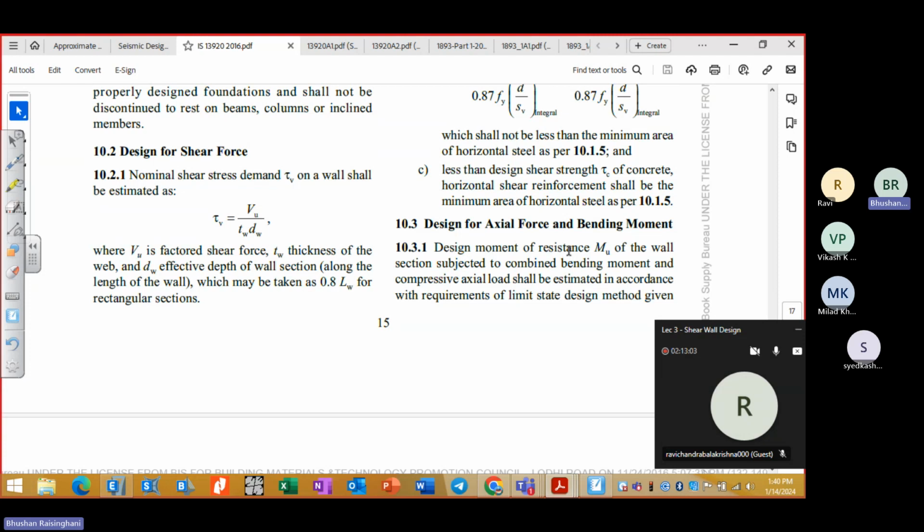There is a P wall software, in which they have given the calculation of how you can find it. So I'll share in the group how they have done it. P wall is a separate software that is based on ACI code for design of the shear wall, and you can compare the results of the two, ETABS and P wall. P wall is purely finite element based software. So PMM interaction curve is required for any shear wall, especially if it is a slender wall.